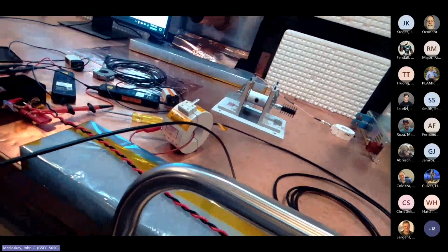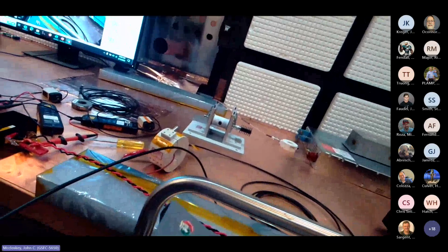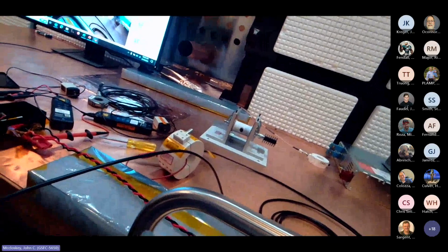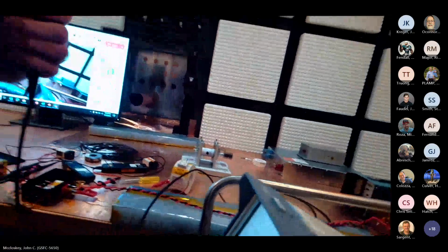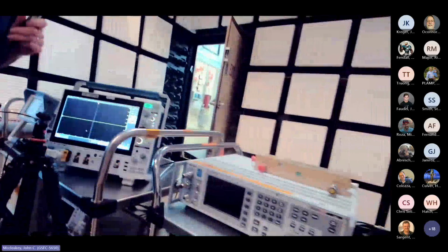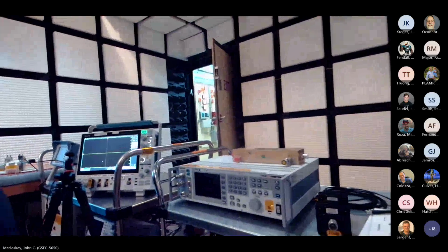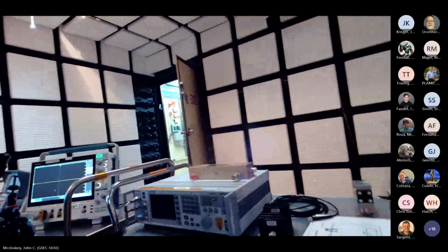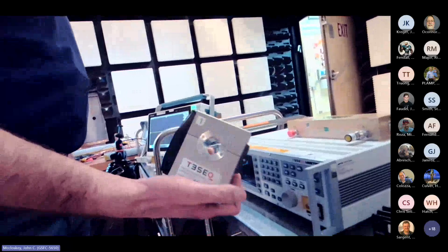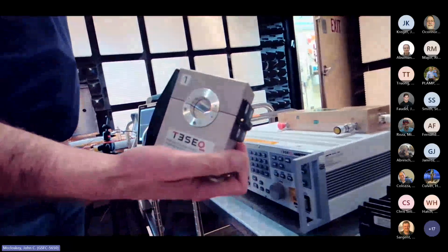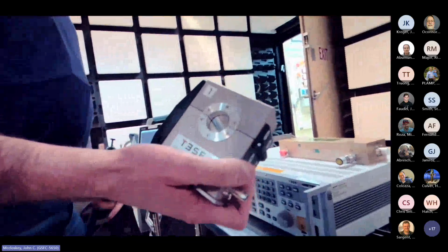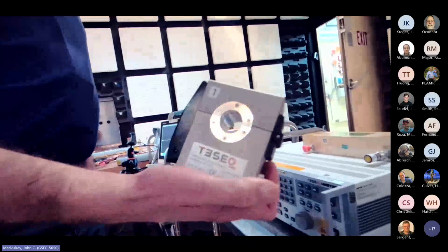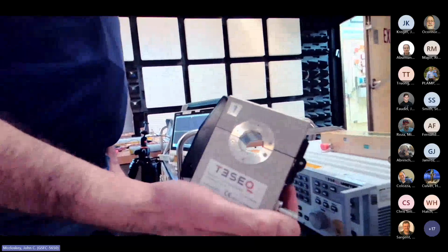And now I want to measure the current. Normally, going into a full up system, which we'll demonstrate another time, you would be using the current probe. Go ahead and grab that. It's show and tell. You can use basically any current probe, but you would have to make sure you've programmed into the system what the transfer impedance of this probe is as a function of frequency.